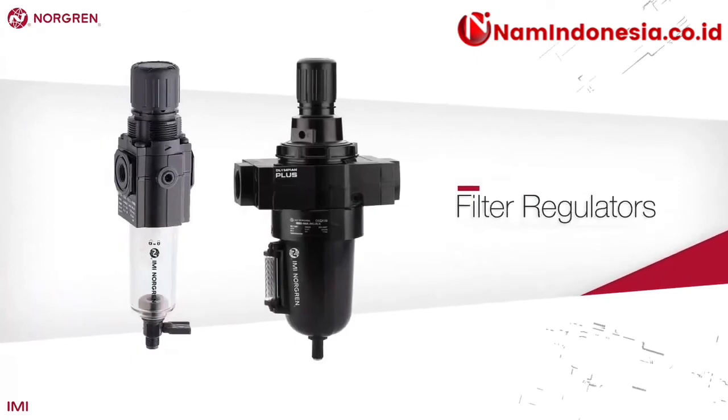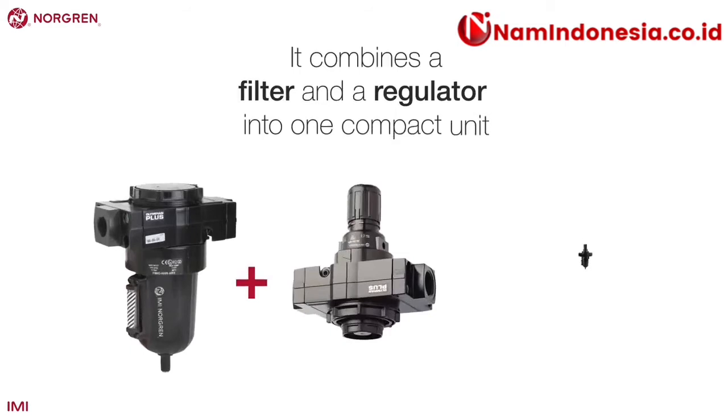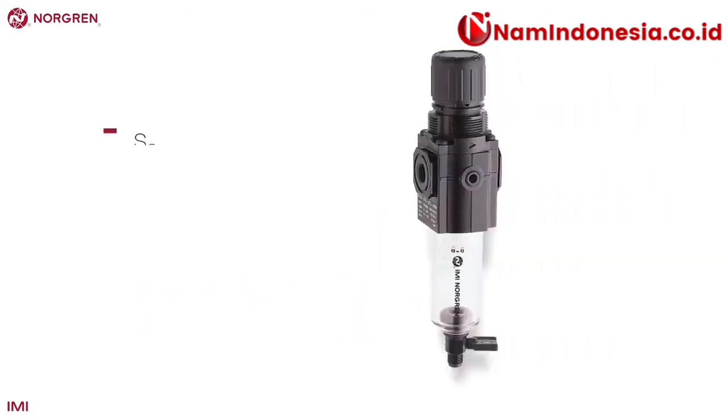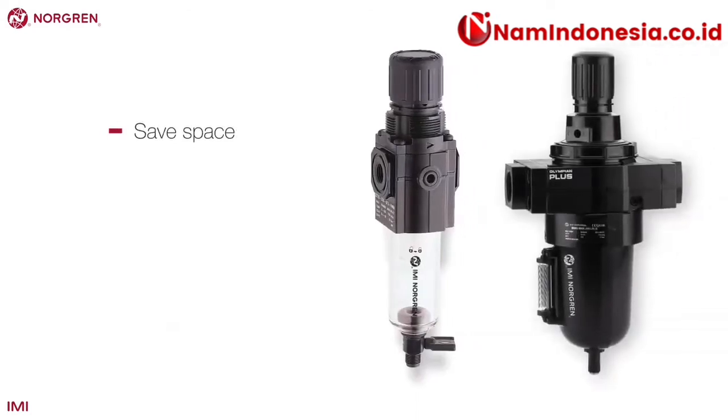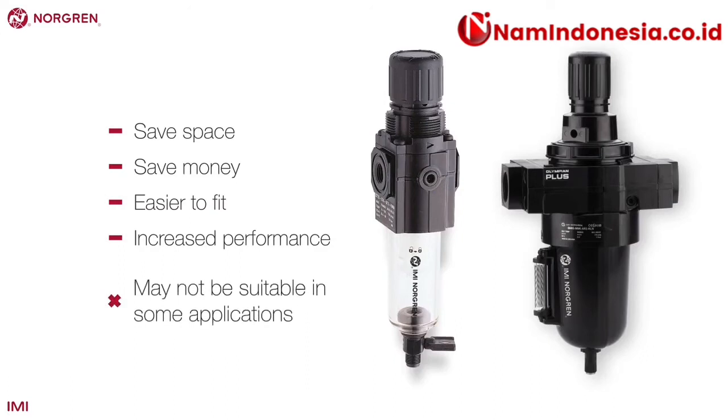The filter regulator is the most popular unit Norgren sell. It combines a filter and a regulator into one compact unit, providing a series of benefits. They save space over having units side by side, save money as the system is cheaper than individual units, are easier to fit, have fewer connections meaning less air loss, and perform better as flow characteristics are optimized. The regulator needs to be on top and they need to be installed upright for the bowl to work correctly. So in some applications, they may not be suitable, and separate products will need to be installed.